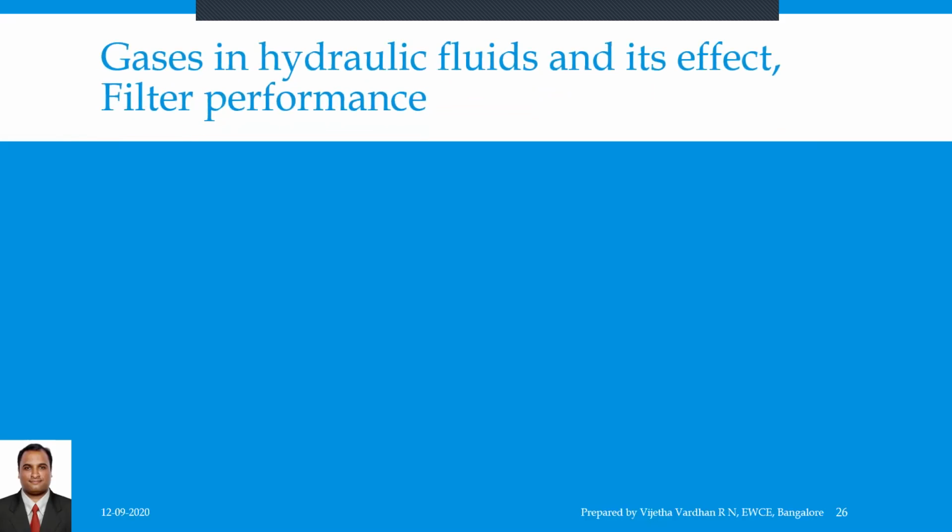Then coming to gases in hydraulic fluids, their effects and filter performance, we are going to discuss now. Very often, gases in the hydraulic oil may create undesirable effects in the system. The gases or air can be present in the hydraulic fluid in three forms: primarily free air, entrained gas, and dissolved air.